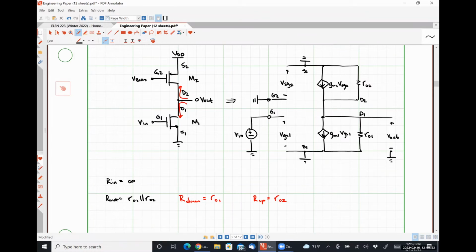So from the amplifier perspective, right, so from our small signal perspective, this current source connected load just looks like a resistor RD having a value of R not 2. So from the small signal perspective, we effectively have the exact same circuit as we had a moment ago. We're just going to replace RD with R not 2.